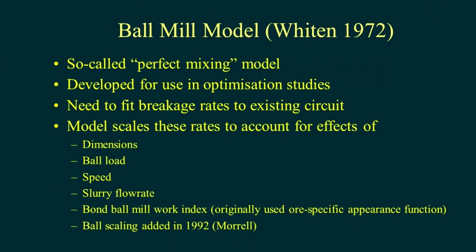Right, ball mill modelling. Bill Whiten, 1972, also at the JK Centre, put together what he called the perfect mixing ball mill model, and that is the model that sits in JKSimMet at the moment. It was specifically designed for you to optimise your ball mill circuit. It was not designed for you to use in a greenfield situation, and I would strongly recommend it is not used by you if you are a simulator for those circumstances,